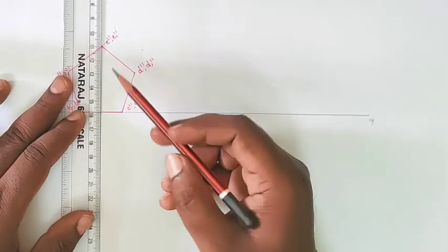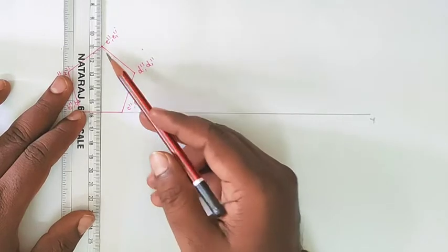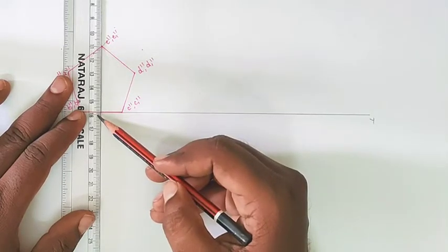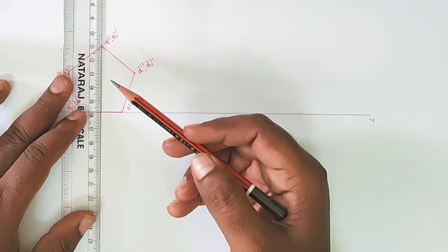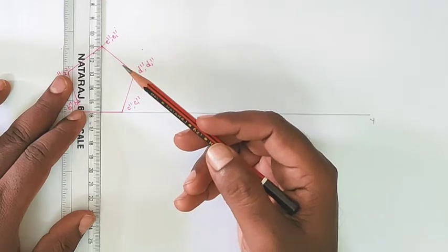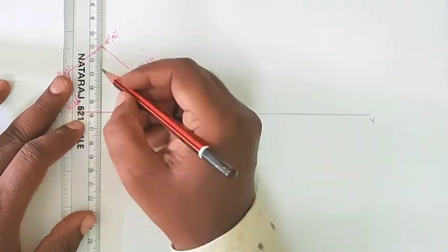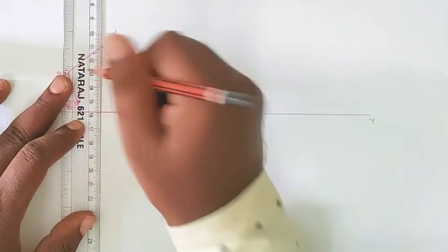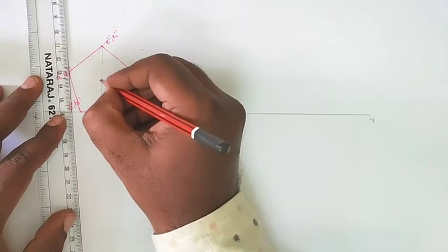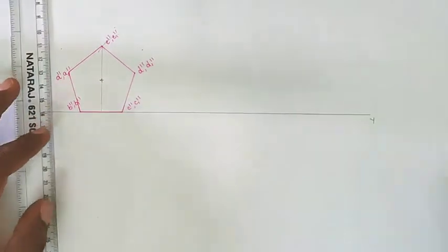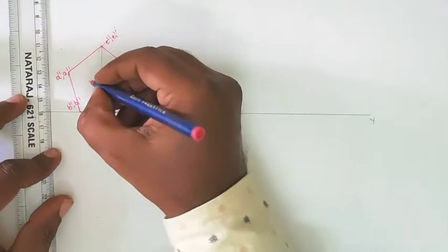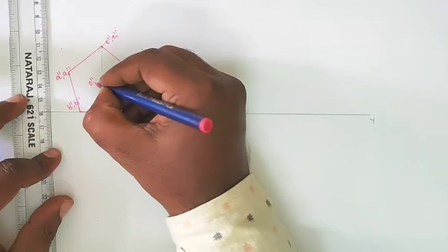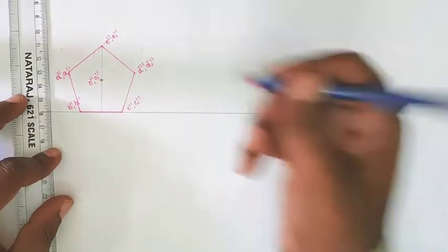This is a simple method. Just identify the fixed corner, draw the vertical line to that side, measure that line length and find out the center. This is the simple way. So take 24 mm here. So this is the center of that side view, o double dash, o1 double dash.